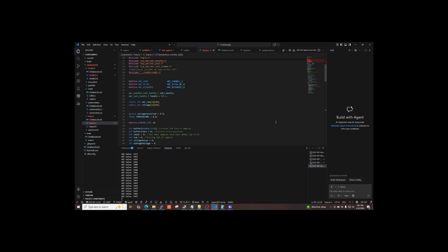So everything's pointing to basically unit 1. So that's what we're gonna have to do. So ADC 1. I mean, it's fine because there's several pins that we could use, and just swapping out because it's an input. Like we could use GPIO 36 for the ADC input, and it would be fine.